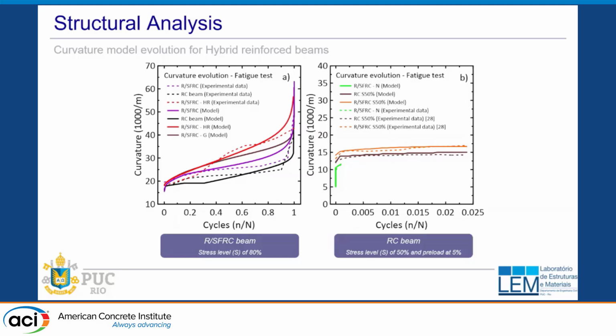Reinforced concrete, initially this way, but then with the experimental data, once you collect the initial cracking and the follow-up for the characteristic definition, we see the curvature ductility that the fibers also bring. So this type of work helps us not only from a design point of view, but also from a better understanding.